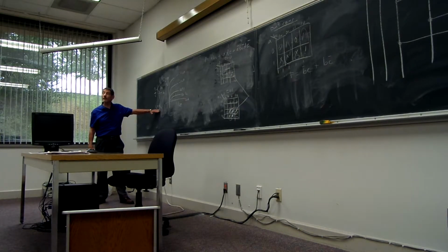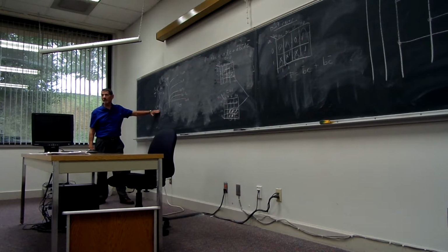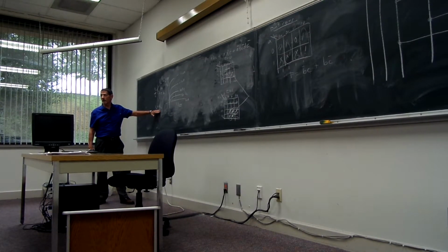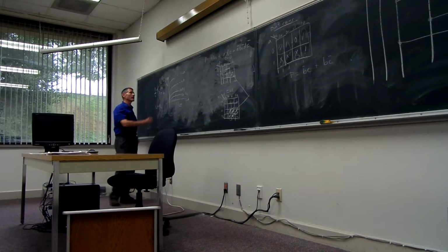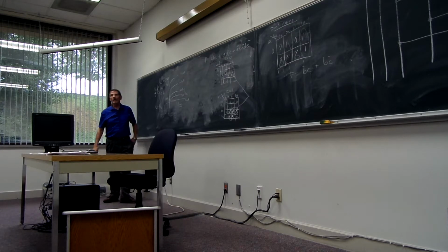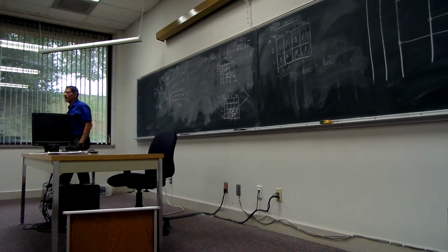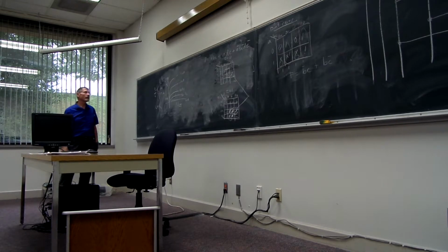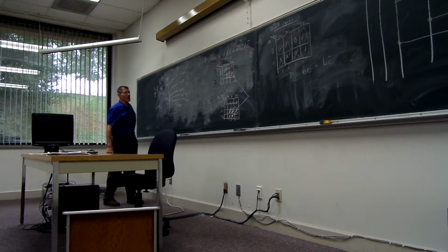Apply this formula where beta is 100. 1,000 microamps, which in most other terminology is called 1 milliamp. 20 microamps in, you ought to get out 2 milliamps.